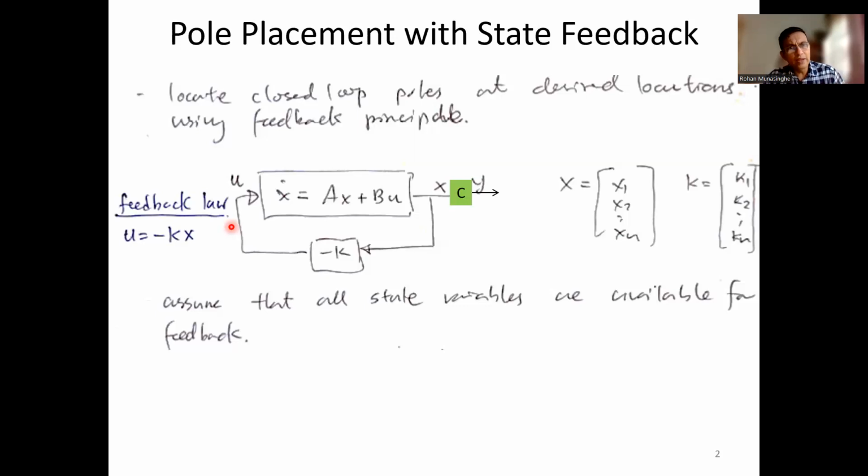And then you have to argue whether this is a stable, rational policy, and so on. You can have any policy, there's no restriction. So in the state feedback, we declare this is our control law: u, the control signal, is equal to minus K times x. Minus K is a set of gains, x is the state.